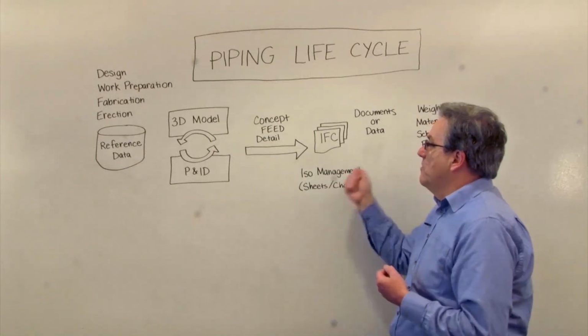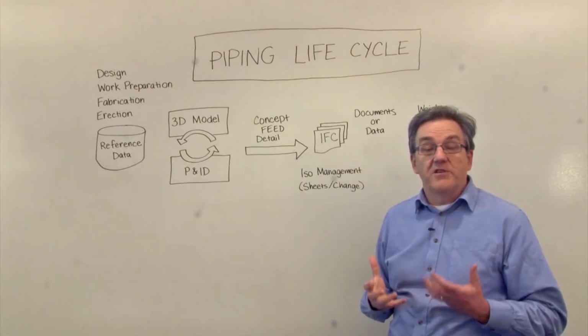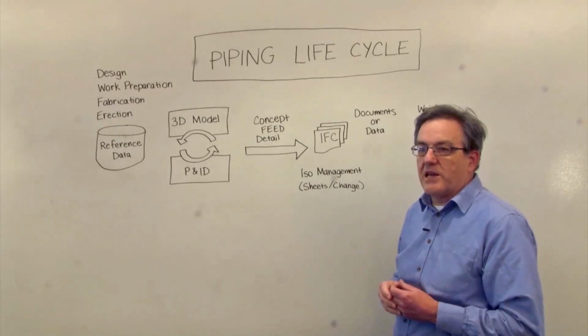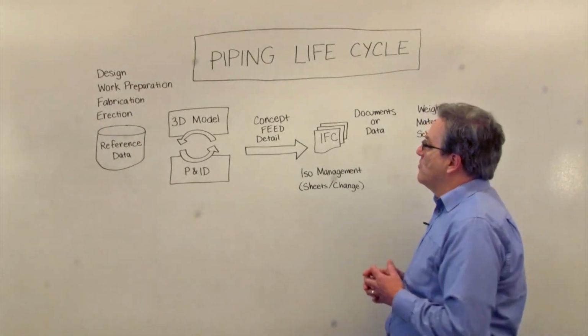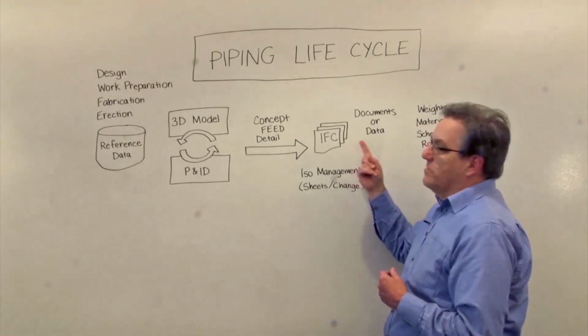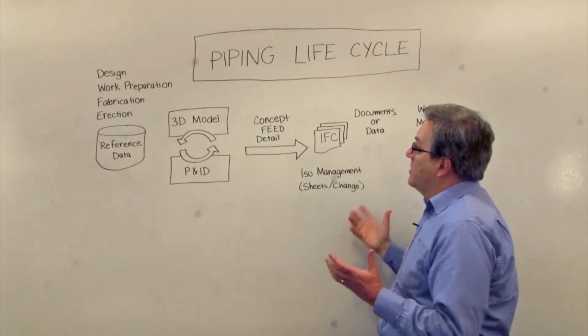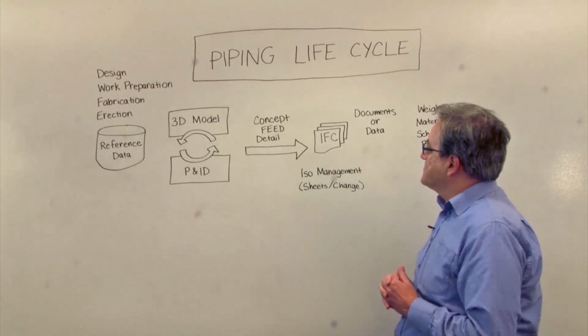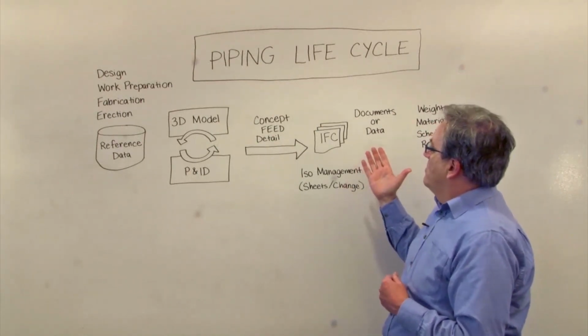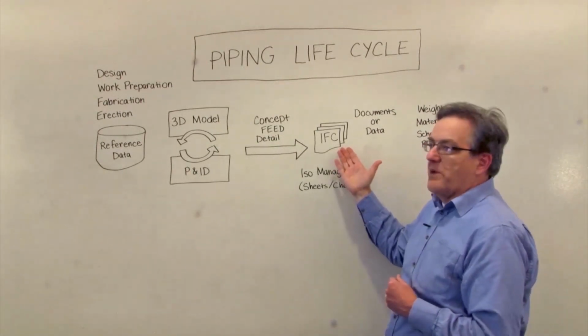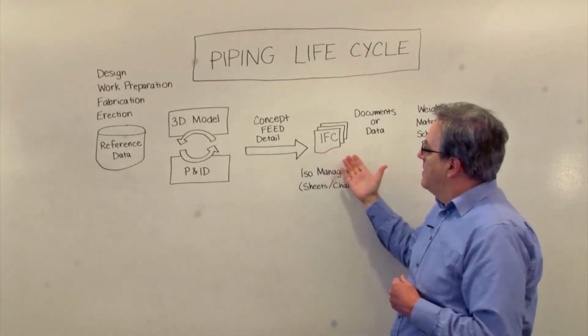So if I've got that drawing, I've got enough information to actually make that section or that piece of the overall piping. And I can be sure that if I follow those instructions when I go to site and erect it, it's all going to work and it's all going to fit. So the piping isometric represents a unit of work.